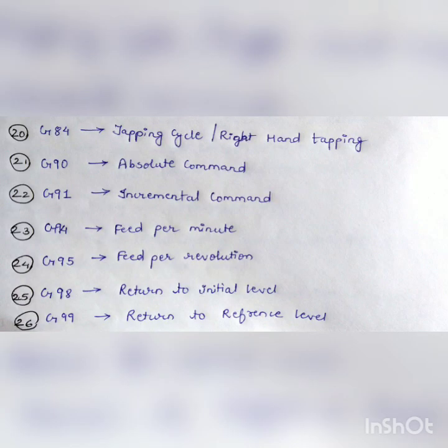G90 means absolute command mode. G91 means incremental command mode. G94 feed per minute. G95 feed per revolution. G98 return to initial level, and G99 return to reference level.